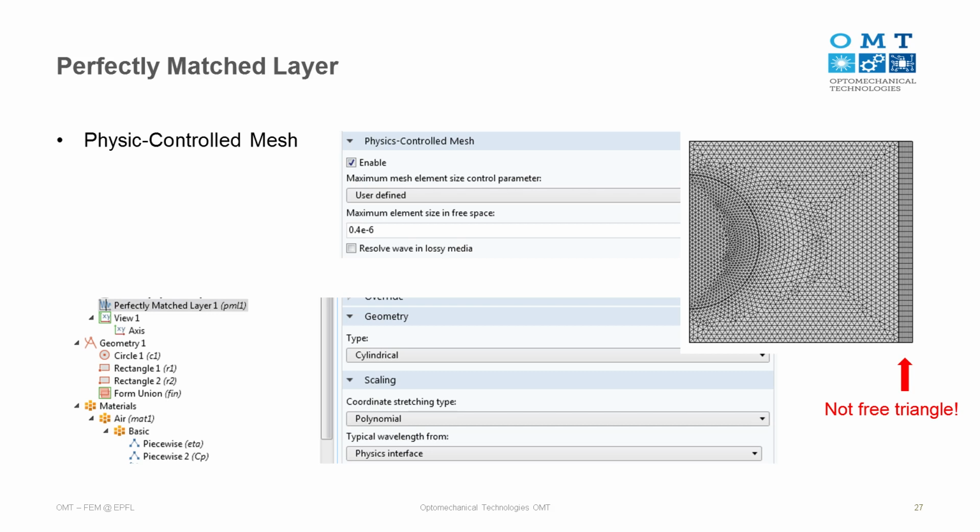But if you use other types, you can have a trick, then it will automatically be defined differently. So it reminds you that if you do the meshing manually, you also need to follow the same way. And physically, it's just because using triangles will give you reflections in different directions, which will be not that precise.